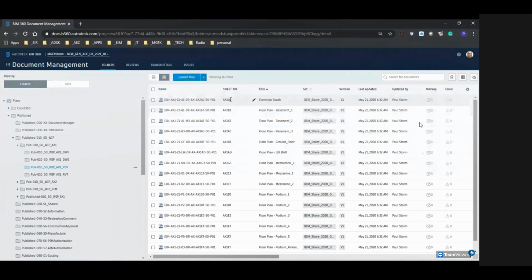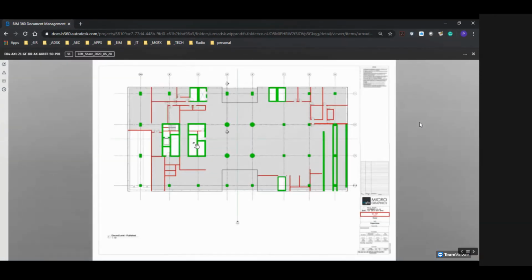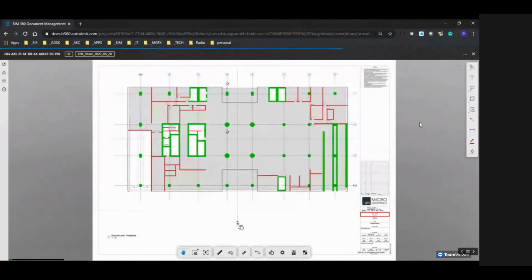So you choose which of your views you would like to publish. You'll see that later with the Revit file. Of course, with the PDF print, it's the same kind of idea in that you choose the drawings that you print, but it doesn't work through publish, it works through the printing command.